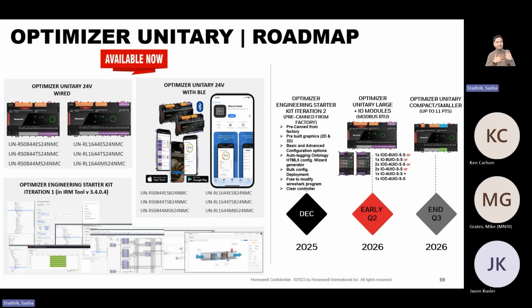And to be honest, when I was a programmer, and I used to integrate VFDs, VRFs of other brands like LG that use Modbus, when you go into the register section, sometimes it just takes one number to be wrong, that you don't know why that thing is not working, and it looks like someone made a typo in the documentation and the register is not that one. So there's no standard. It's so open, nice, but having free for all, then is a problem. It becomes a problem.